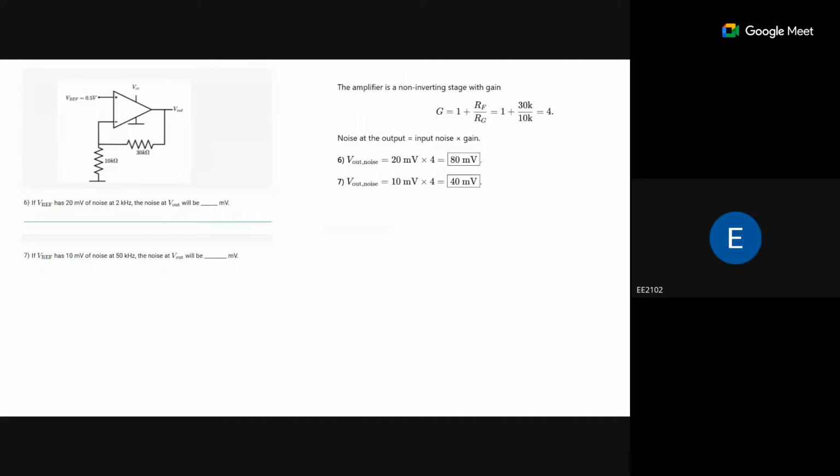This is a regulator where we have seen that the amplifier works, and this is not that different from your operational amplifier, whatever you have studied in other lectures. Here you can see this has a reference voltage of 0.5 volt, and you have R1 and R2 values. The question is what will be the V out given the reference voltage. This is easy for you to calculate, as it used to be for a normal op-amp.